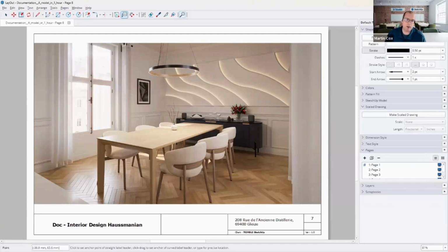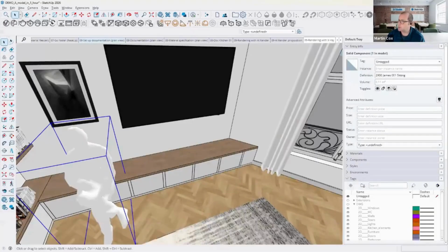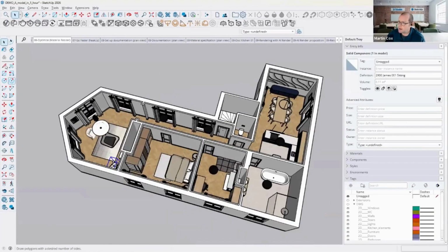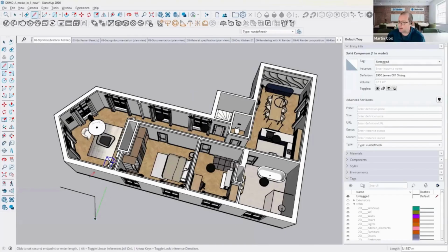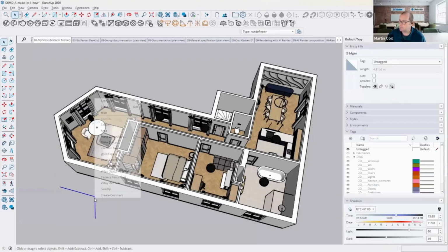So the page for DWG scale, does that mean around the learning? That's learn.sketchup.com. If you go to that, there are some tools there as well. The weld tool, yeah, that's a standard SketchUp tool, welding those lines together that we had. So if I quickly go back to SketchUp, I'll be as quick as I can here. When you draw lines like that, once you select them, right click and say weld edges, and that will weld those lines together.